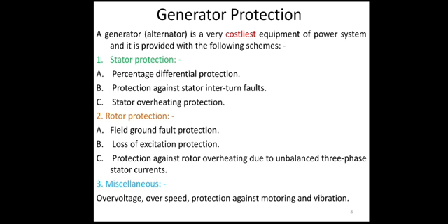The next topic is rotor protection. For the protection of rotor, basically there are three types of schemes. Firstly, field ground protection. The next one is loss of excitation protection, and the third one is protection against overheating due to unbalanced three-phase stator currents.